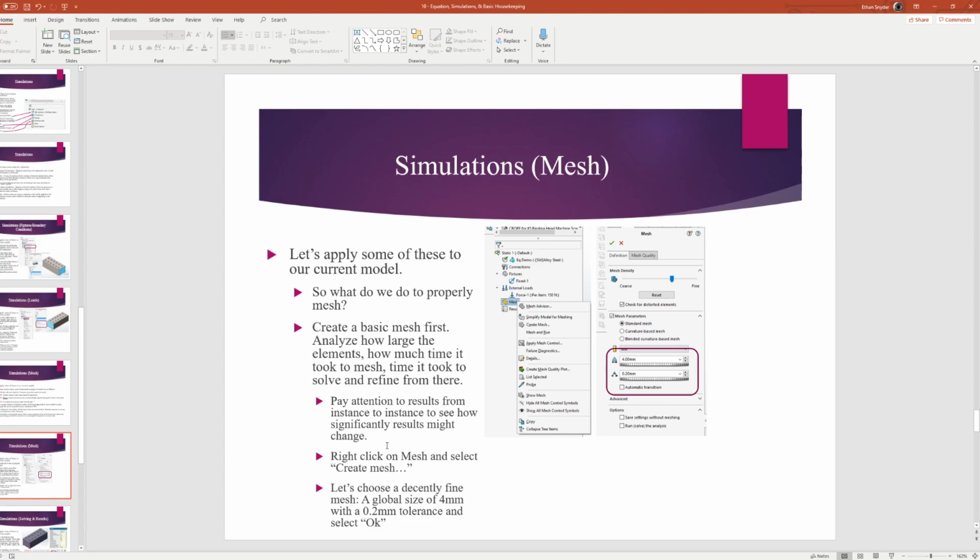You can say, okay, I did one simulation with, say, 20,000 elements and got some results. Then I tried it with 30,000 elements, so I decreased the size of my elements, but maybe the values I get are within a tolerance of a thousandth or a 10,000th, or even smaller than that. It's kind of up to you.